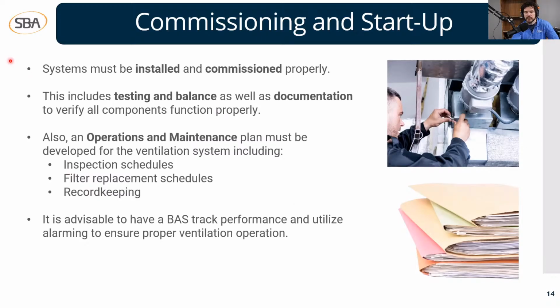Now, once everything is designed, built, and installed, the job still isn't done. Now it's time to commission. So we've got to verify a few things. First, we got to make sure that air is actually flowing as designed. We also need to make sure that our dampers are open and closed.